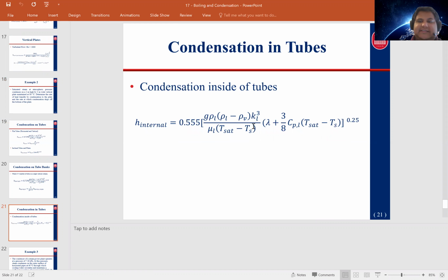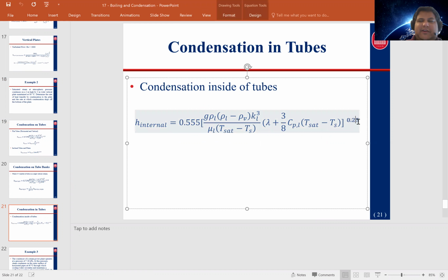It looks kind of like this, but I would argue that's probably not going to be the most efficient use of a heat exchanger, in that you're going to have less surface area for condensation, and there's no real place to go as the material condenses, right? Because over time, if you're condensing inside the tube, you're eventually going to have a film take up the entire interior of the tube, which means you're going to have more and more heat transfer resistance associated with the phase change.